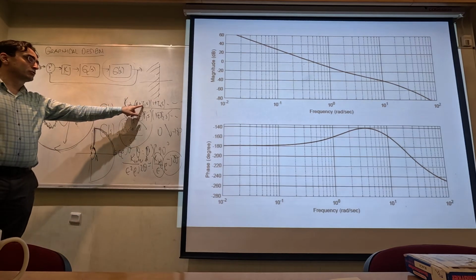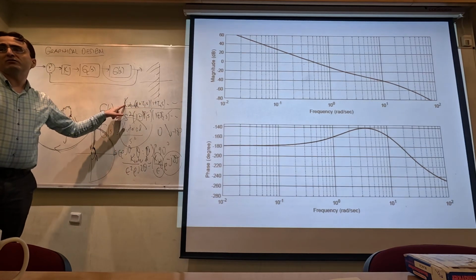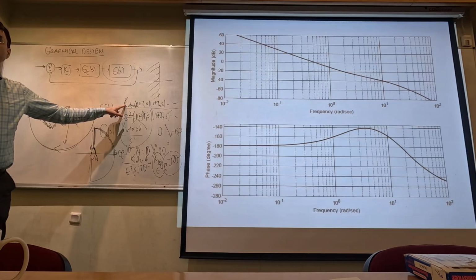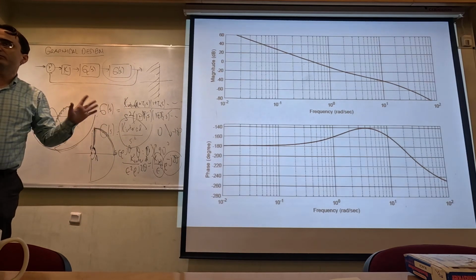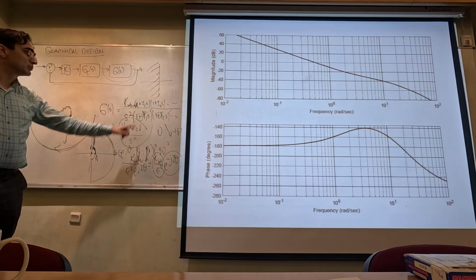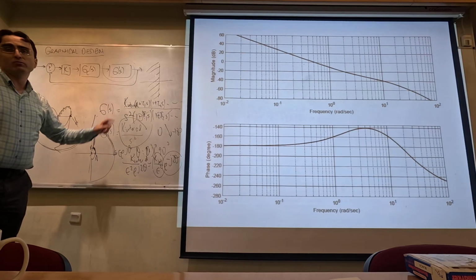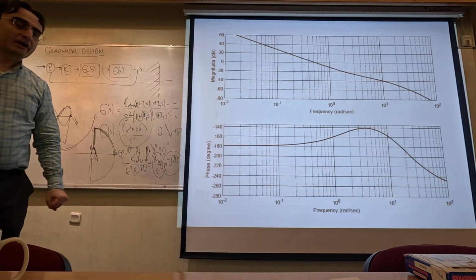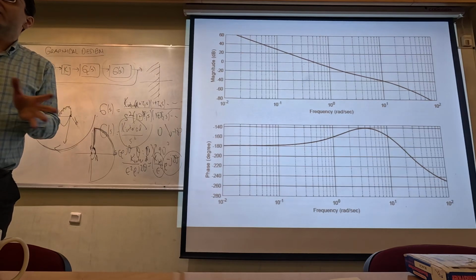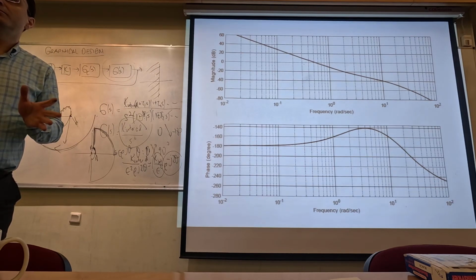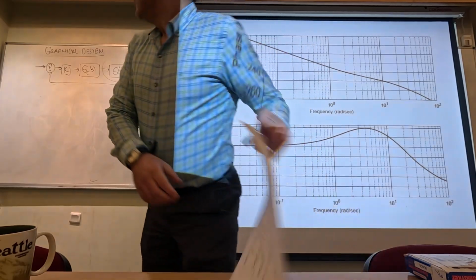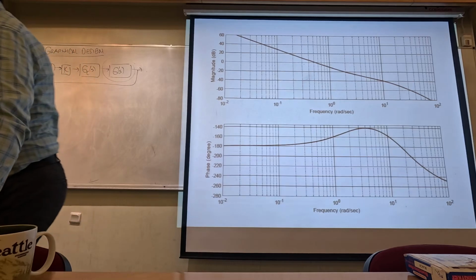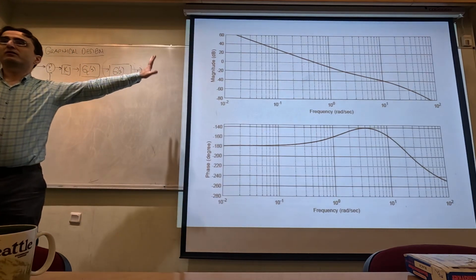We always have positive signs here, and we always have a positive internal gain for the Bode plots. Otherwise, the Bode plot would be meaningless. It wouldn't make much sense to draw a Bode plot when there are minus signs here, or when you have negative gains. In that case, phase margins and gain margins would lose their meaning from the Bode plot. But in the Nyquist plot, everything is possible.